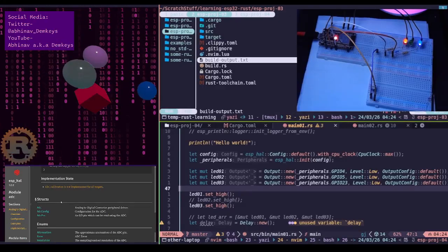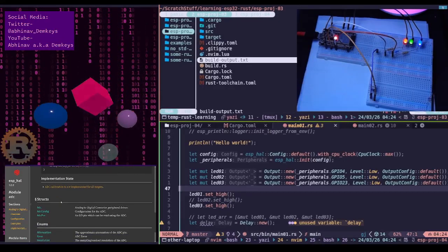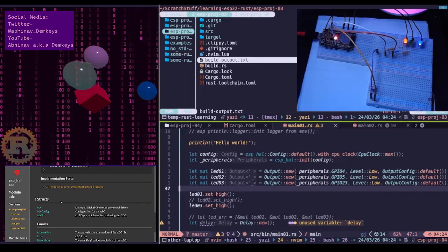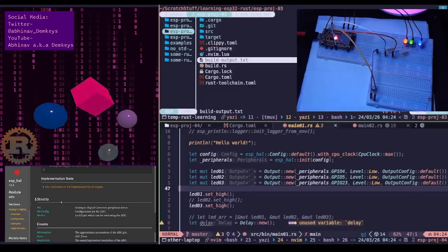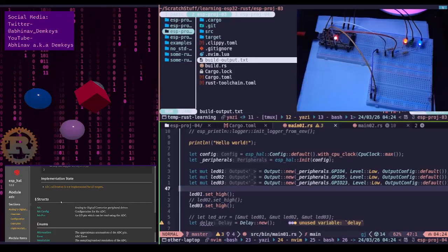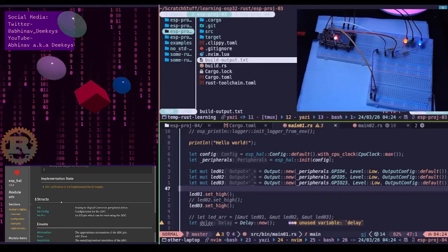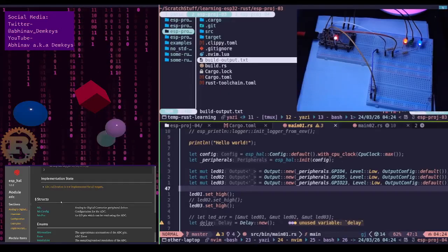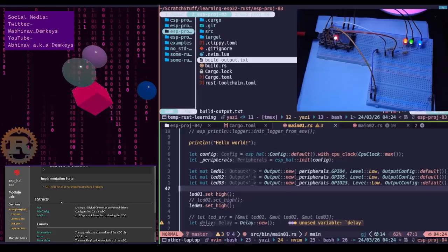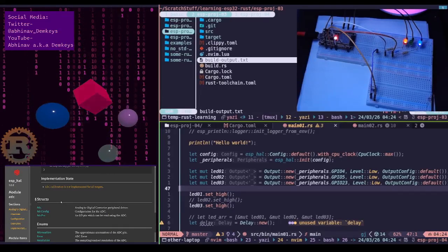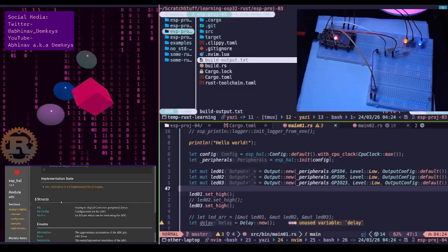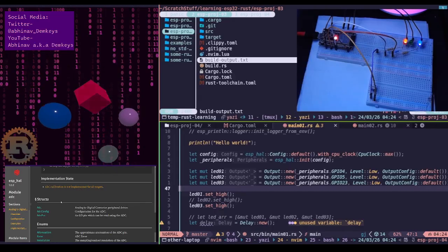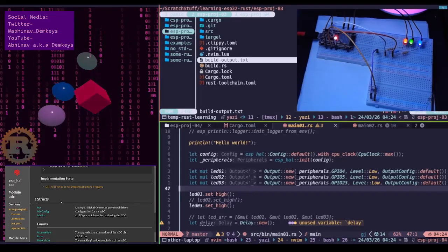Good to know. So now we are going back to potentiometers. Yes, so this is where we had come to the question about calibration. In here, it mentions that when you connect pin 1 to 3.3 volts, pin 3 to ground, and pin 2 to GPIO 4, then you get these different values at different stages.